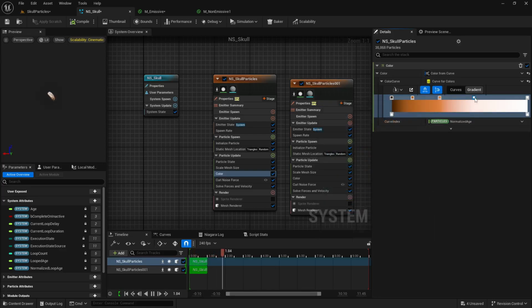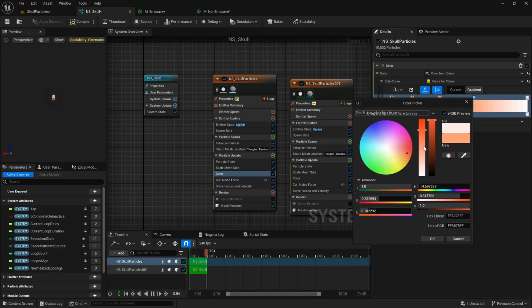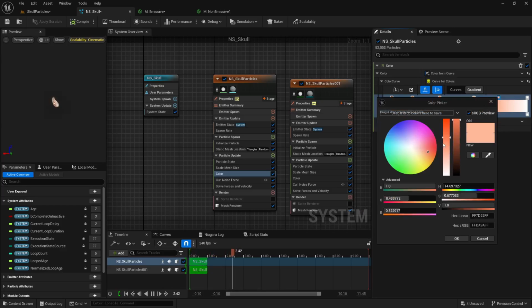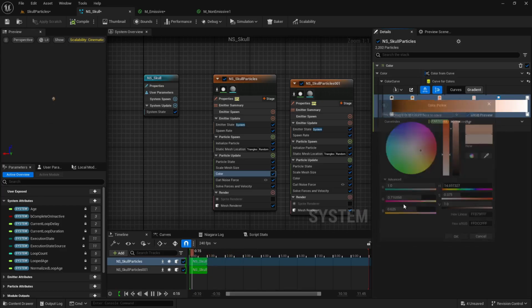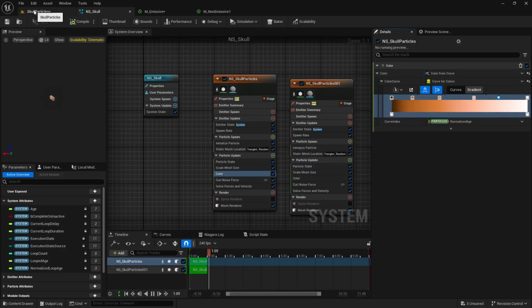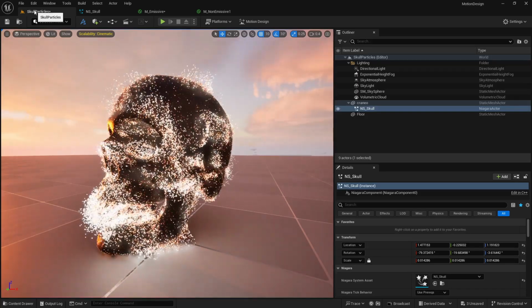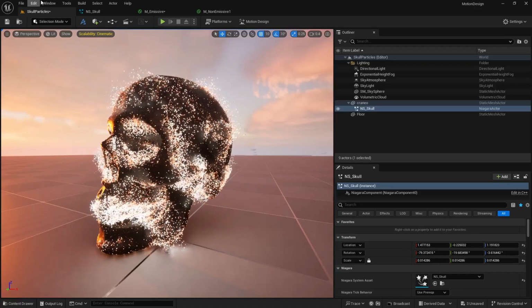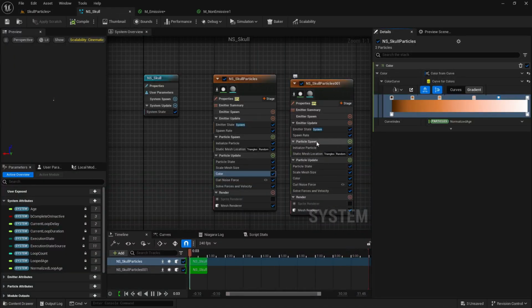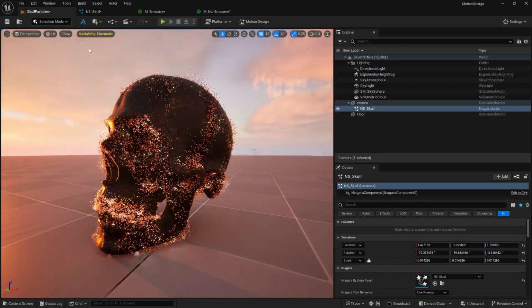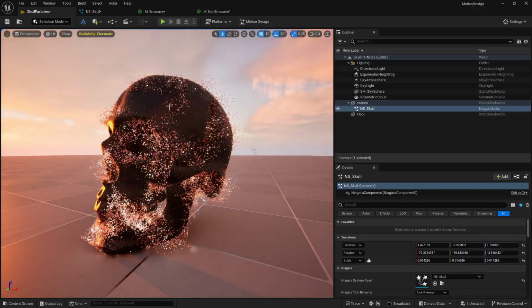Okay, if I do something like this here as well, then let's add one more point here. Let's save it and now see. So now you can see the result here as well. I think 12,000 is a bit more in our emissive. So let's take the spawn rate to maybe 500, so we don't get so many particles. Now you can see we are emitting just some particles.